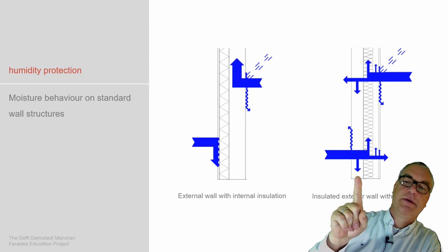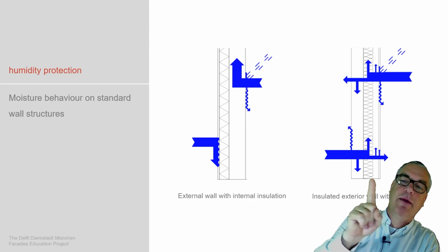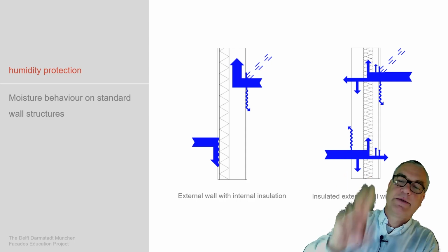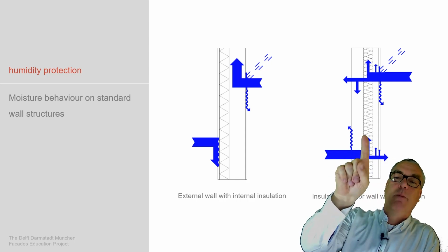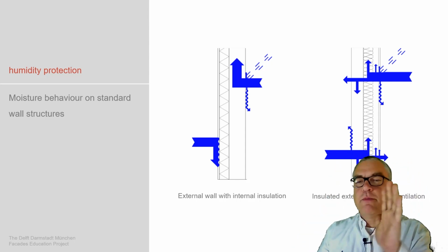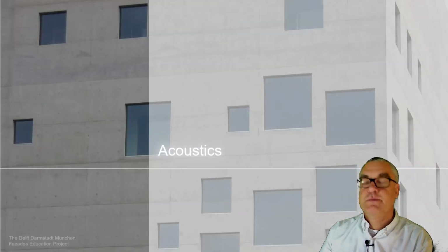and we can see this ventilated cavity facade, which means there's an outer layer which is a rain protection. If there's any humidity in the system, it finds its way down here, and then there's the insulation which rarely takes humidity, and then the inner wall system which takes some humidity. But you see at the top drawing that the humidity from outside is mainly blocked by this system. This is why they say technically they are so well performing in this respect.